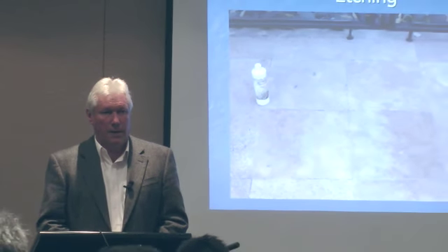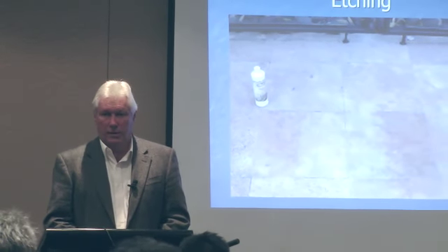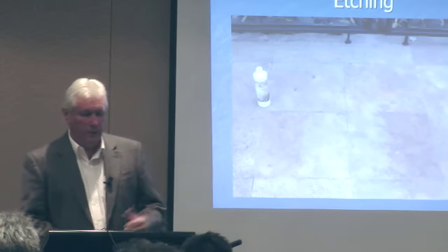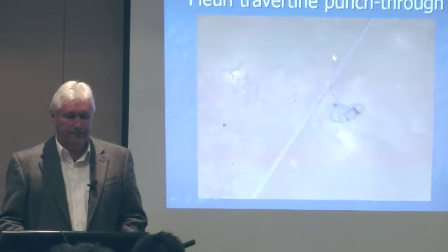It's not a really good photo, but in this case this is a Sydney site where the person had a honed travertine outside. They weren't advised that the travertine is sensitive enough to react with acid rain. So the rain in Sydney is sufficiently acidic so that all the areas that weren't under the eaves of the house lost their shine and started to go white. They could be restored with a bit of a rub, but it's going to happen again. It's very difficult to protect. There are some mechanisms there for protecting against acid attack, but most of them are not really very good.